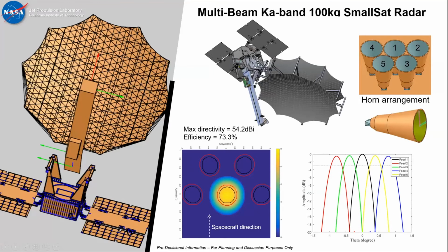So, like I said, I discussed these very nice demonstrations that we achieved using these two CubeSats, the radiometer and the RainCube active radar. And as a result, we are now considering launching a small sat that will fly these two instruments as such with no modification. We will have the radiometer and the RainCube instrument co-located on the small satellite, and we will deploy a much larger antenna for the active instrument for RainCube. This one will be about 1.6 meter, which will allow us to have a much smaller footprint on the ground and as a result, a much better resolution.